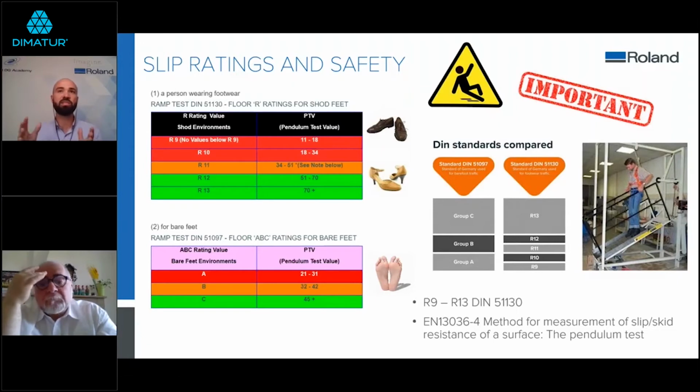So as we said, there are these DIN ratings, and then there's the pendulum test. So do talk to your media suppliers about the rating and about the insurance or liability you might be exposed to where you're putting your graphic. If this is in a high foot traffic area, are there insurances in place? Are you liable for the graphics going down? So as I said, talk to the media suppliers and do be sure to research the different R ratings or the pendulum test ratings in your region or locality as well.